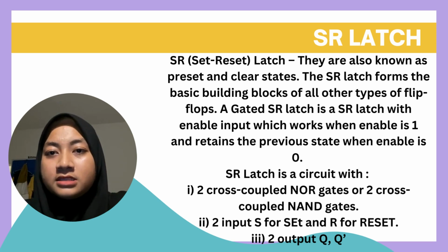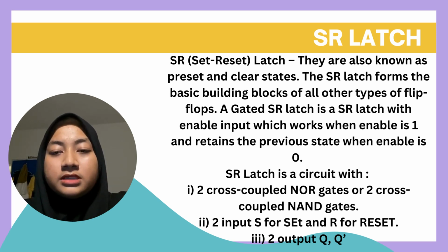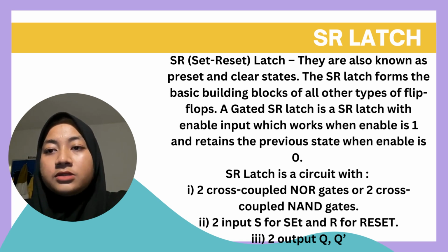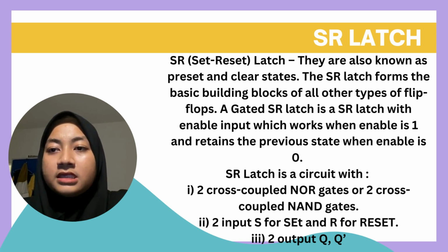In an SR latch, S is for set and R is for reset, as I mentioned before. They are also known as preset and clear states. The SR latch forms the basic building block of all other types of flip-flops. A gated SR latch is an SR latch with an enable input, which works when enable is 1 and retains the previous state when enable is 0.